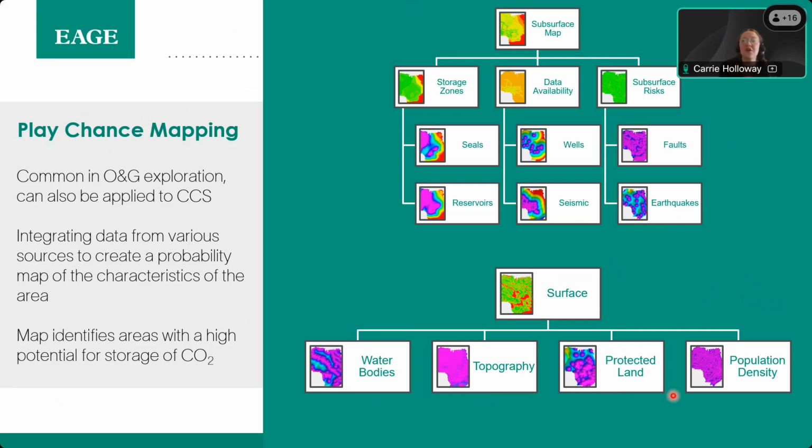In a lot of locations, we do have deep subsurface data, mainly thanks to the oil and gas industry. But obviously in areas where we don't, we may be able to get some sort of magnetic or gravimetric survey to just try and understand the depth to basement, because that could be a very minimum criteria, just finding out that we had the sedimentary depth to store the CO2. But really, if we don't have any subsurface data, we're going to struggle. So thank you for your question.